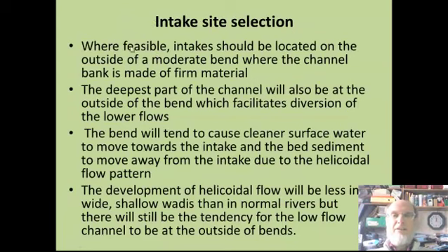Selection of intake sites. Where feasible, intakes should be located on the outside of a moderate bend where the channel bank is made of firm material. The deepest part of the wadi channel is also going to be at the outside of the bend, so it is easiest to divert the lower flows. The bend will cause the cleaner surface water to move towards the intake and the bed sediment to move away from the intake due to the helicoidal flow pattern.